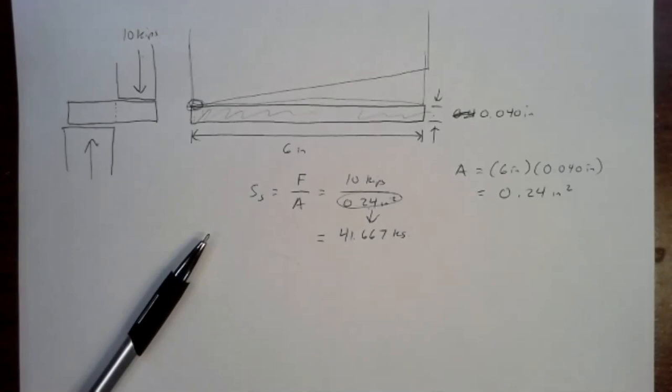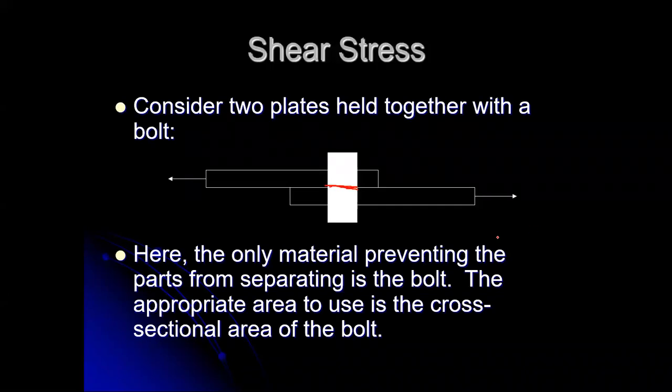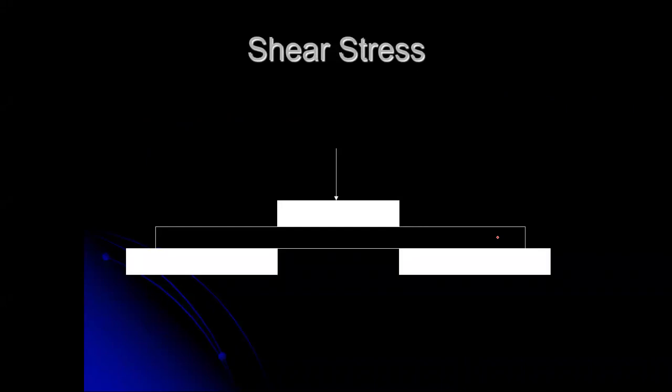So let's see here. That's another example of shear stress. So there's the punch example. This is similar to what I just showed here with the sheet metal shear. If you have a die block that is just a little bit smaller than the hole down here that it needs to fit in, you push down hard enough, this is going to poke through.